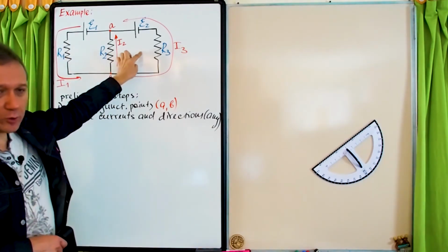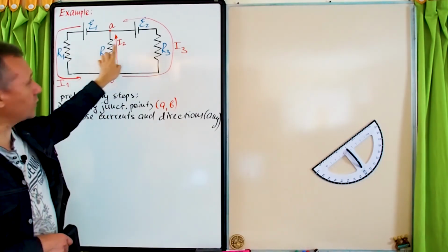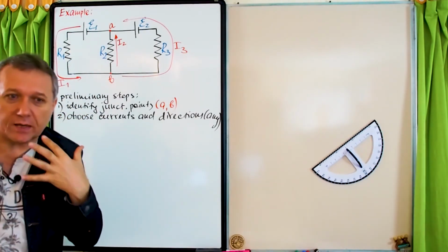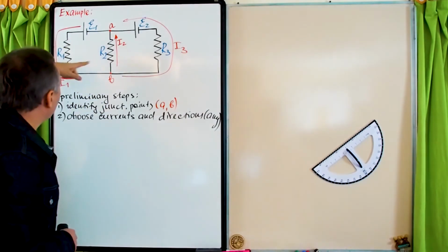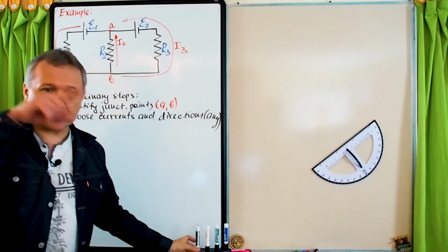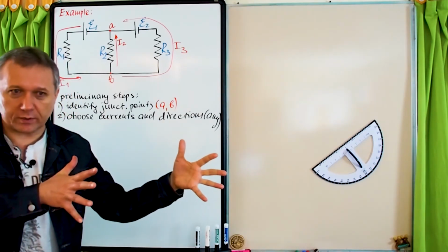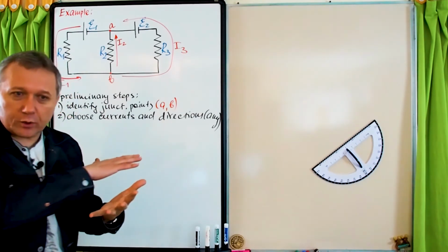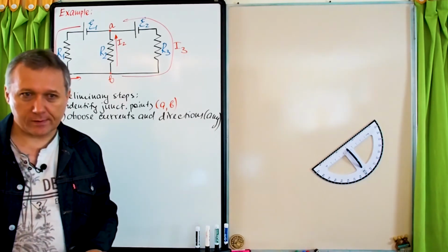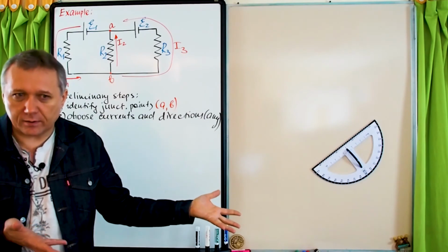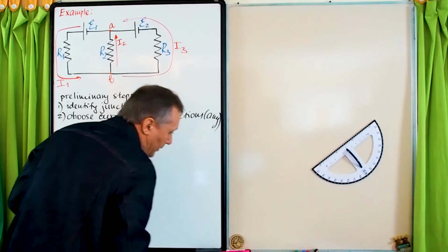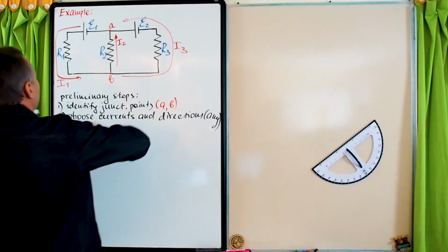This loop and that loop is enough. Right. So, okay, let's label this loop number 1. In travel direction, again, it doesn't matter which direction, clockwise or counterclockwise. Again, as I said, the difference between this direction and that direction in the equation which we are going to write is just like multiplying the whole equation by -1. It's just changing the signs next to each term. Equations will be still the same, right? So that's why, which direction do I pick? I picked counterclockwise. Okay, let me use green.